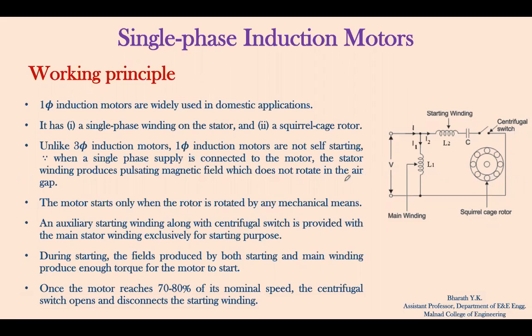Unlike 3-phase induction motors, single-phase induction motors are not self-starting, because when a single phase supply is connected to the motor, the stator winding does not produce a rotating magnetic field, but it produces a pulsating magnetic field which does not rotate in the air gap. Therefore, the generated positive and negative torques cancel each other and the motor doesn't start. The motor starts only when the rotor is rotated through by hand or by any other mechanical means.